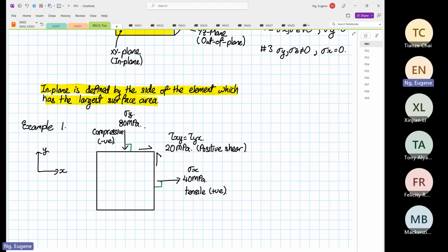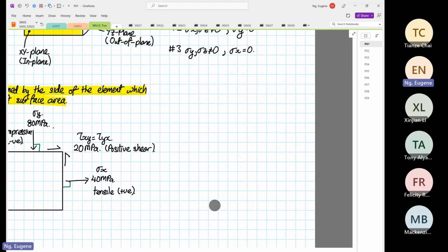It's not like in normal stress. Sometimes tensile stress is no good for brittle material. Usually for compressive stress, the yield strength is higher. In shear, positive or negative shear is as good or as bad. You cannot say that this material can withstand higher positive shear or lower positive shear. It does not apply to those rules. So why do we call that positive shear?